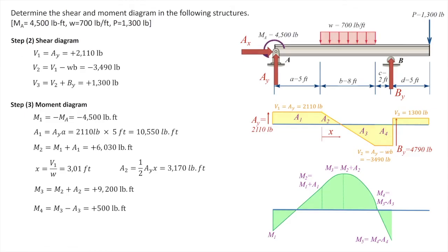Moving to the right side of support at B, there is no jump on the moment diagram because there is no concentrated moment, but now the moment goes upward because the area under the shear diagram is now positive, and the increment would be linear because the shear diagram is constant.